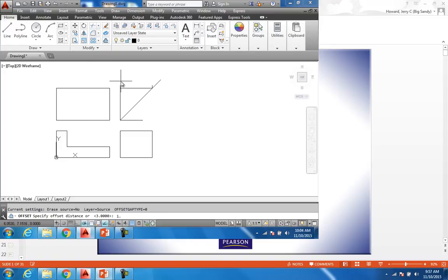Offset 1.75. Go ahead and put this little fella in right there. It's that little angle that's on the side of it. And I want to bring this on up here like this to there, because I know on the top view it's going to start right there and come over, and it's a quarter inch off of this side. Offset to the wrong side, so I'll try it again. Alright, so we got that one. So I just clean up those lines I didn't need, trim.